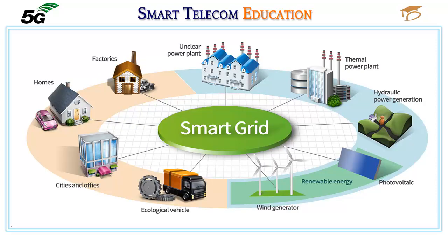Smart grid. The smart grid has strict requirements of reliability and latency. The dynamic control allows only 100 milliseconds of end-to-end latency for switching suppliers. However, in case of asynchronous co-phasing of power suppliers, an end-to-end delay of not more than 1 millisecond is needed.